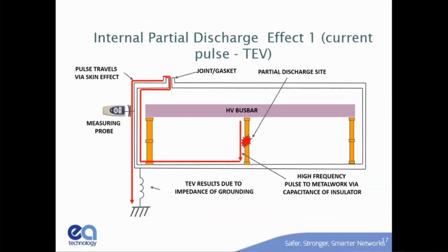So TEV, like I said, this is the most unbelievable thing I'm going to talk about today. If we have some high voltage component inside a grounded metal box, and it's held off the inside of that box by some sort of insulation, obviously I've drawn this really simply, and I have a discharge site. Remember my 3 capacitors. If I have a discharge site in the insulator and I get a current, it's going to flow through that insulator to the inside wall of the box. And that box could be switchgear, it could be bus compartment, it could be unibus, it could be shielded cable. I don't care. But what happens is it won't go through the metal. At these frequencies, it's such a narrow pulse, it has to have the free electrons that are on the surface of the metal to travel. So it travels on the surface, inside the surface of the switchgear, until it finds a way out. And our switchgear is not sealed, welded shut. So there's joints, gasket, bolt holes, things like that. It finds its way to the outside of the gear.